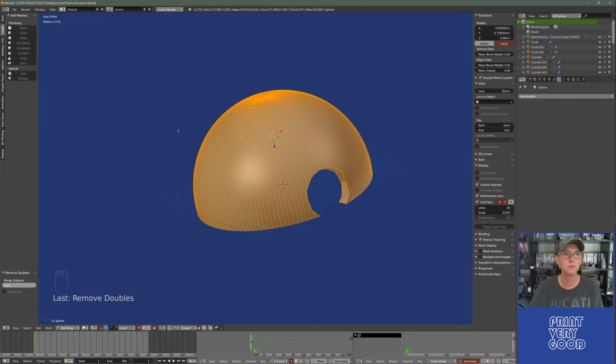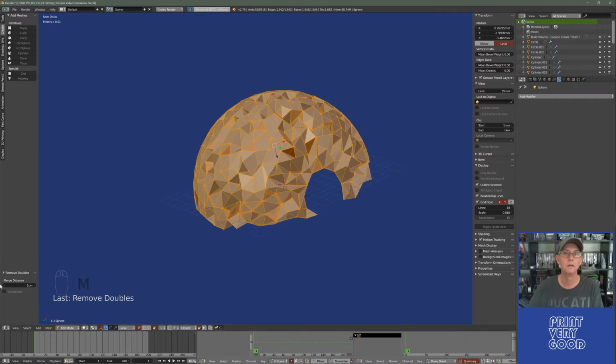And if you look at the top of the screen, it just briefly told you how many vertices have been removed. If I make this 10 millimeters, you can see here it's removing 16,000 vertices and merging those together. So it's creating a much coarser mesh. But while you're still in edit mode, and you haven't pressed the enter key or gone back to object mode, you can keep changing this tool setting as long as you want. So I'll take it back to 1 millimeter.